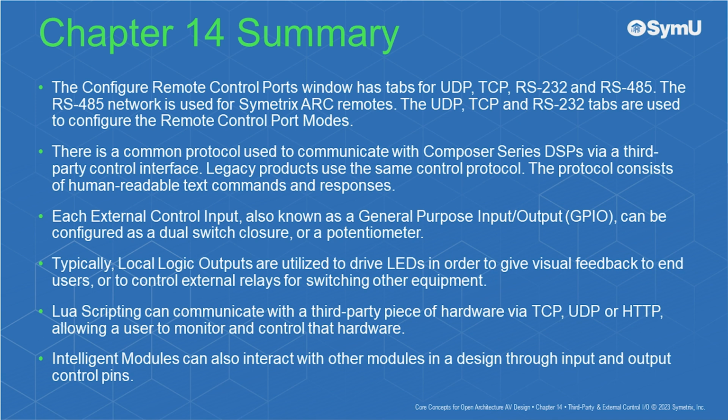Each external control input, also known as a general-purpose input-output (GPIO), can be configured as a dual-switch closure or a potentiometer. Typically, local logic outputs are utilized to drive LEDs in order to give visual feedback to end users, or to control external relays for switching other equipment.